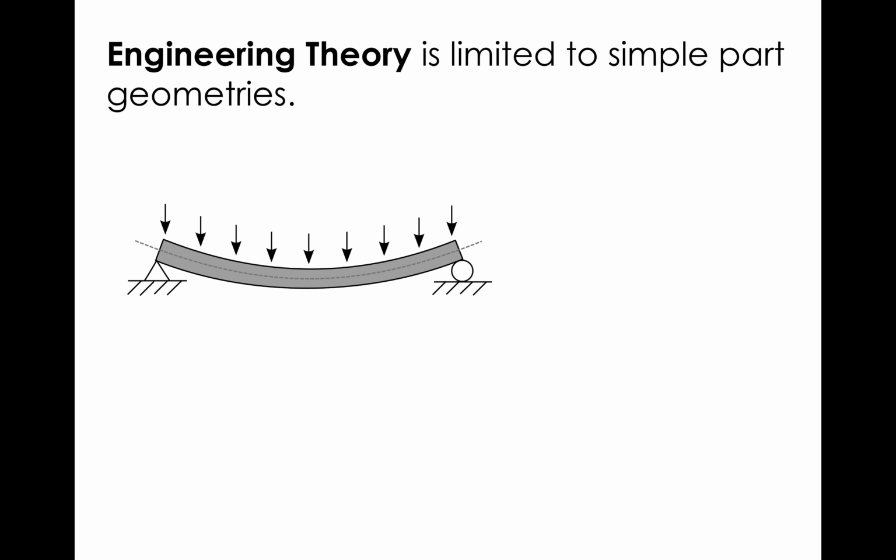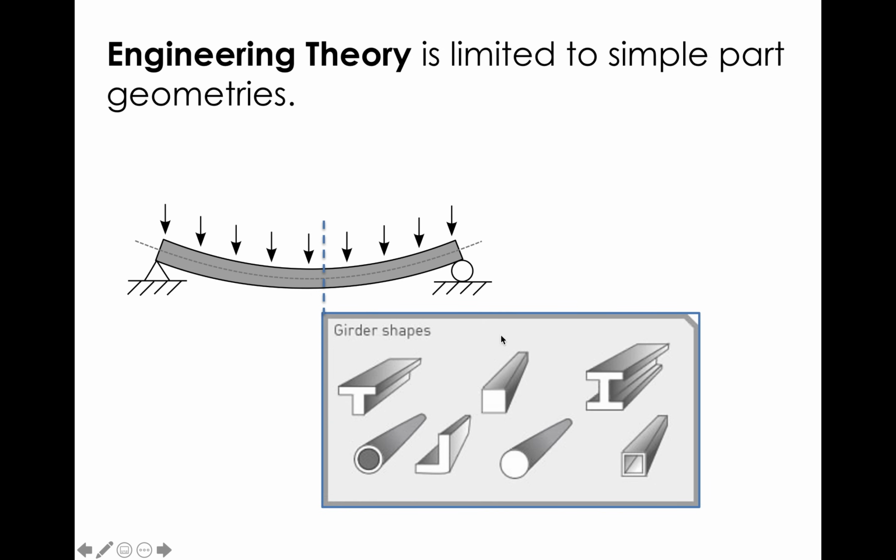Okay, so you can calculate that I for a number of shapes, and these are shapes that you're going to see over and over again as an engineer. If you look up into the ceilings of buildings with exposed ceilings, or in your house, you may have an I-beam that runs across the foundation. Okay, that's a very common shape. It actually has a really high moment of inertia, a high I, on an I-beam for low weight, which is why it's used. But any of these shapes, you can actually calculate I, and you're going to spend a lot of time in MEEG 215 doing those calculations. I'm sorry, it's kind of a pain in the butt.